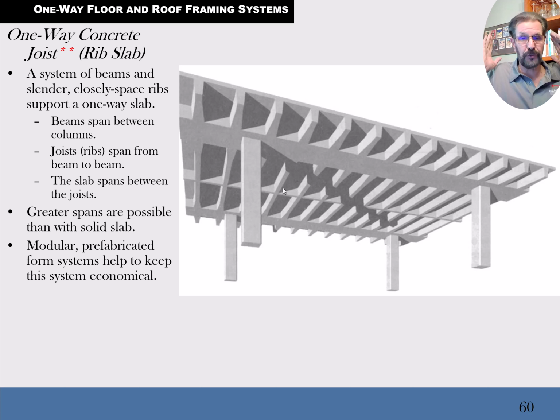All the principal structure of supporting is going one way. Well, you might say it's going left and right, or to and fro, or whatever. But the point is it's like ceiling joists in wood framing, or floor joists in wood framing of 2x12s. That's considered a one-way system, going across in that direction, as opposed to going both ways.